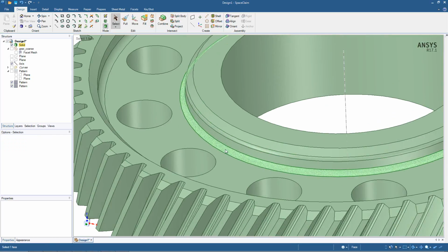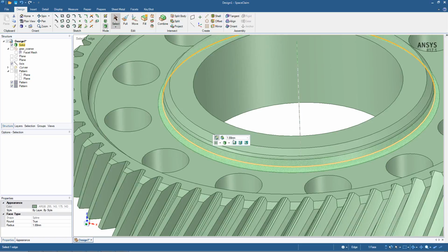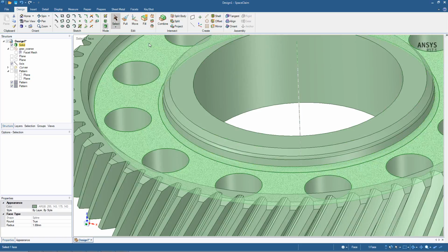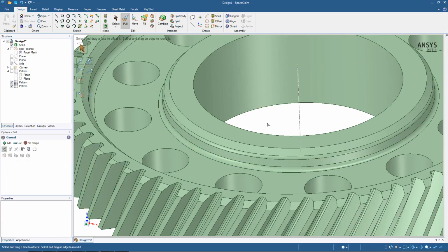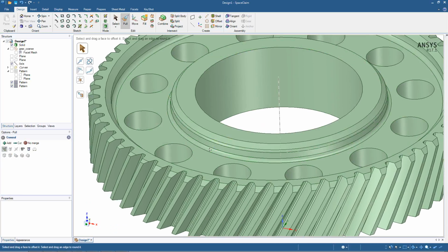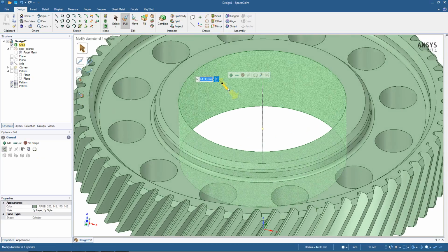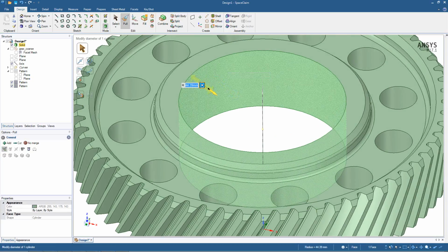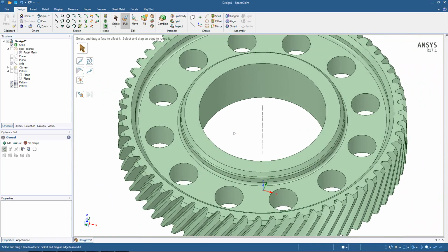If you click on this surface right here and see that it shows up that it's 1.88 as the radius. Well, maybe that should be say 1.75. Just simply change it to whatever you would like it to be, or what it would be in real life. Maybe it's slightly off just because of the faceted data that we worked with. Same thing with this inside diameter, 44.39, maybe it's supposed to be 44.5, let's say. So you can easily make any of the changes.